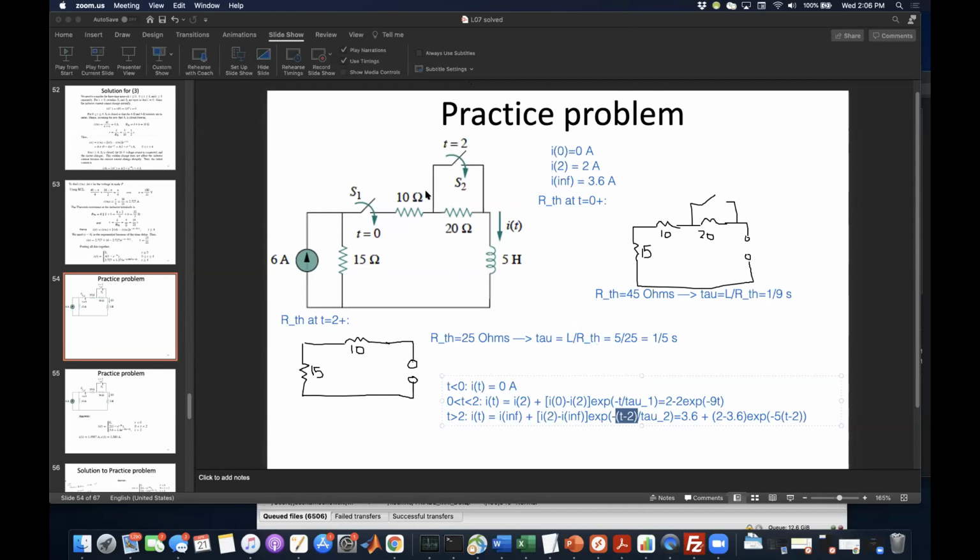So basically, if you think about the second switch, that second transient, separately from the first, you have your initial value of 0. That first switch flips, and the current goes from 0 to 2 with a time constant of 1/9 of a second. Halt everything there. The next thing that you do is you pretend that that value of 2 is now your new baseline.